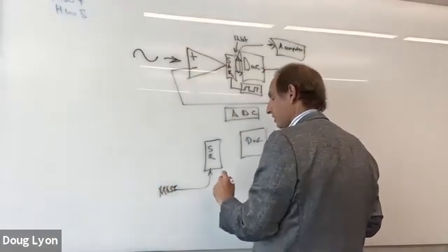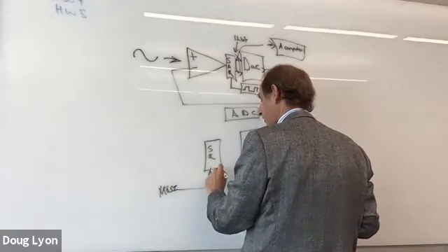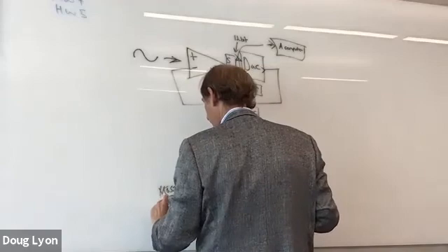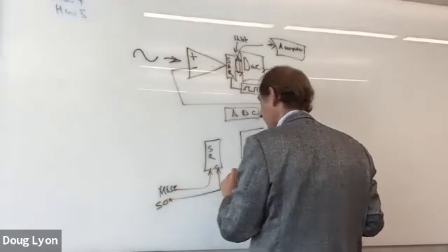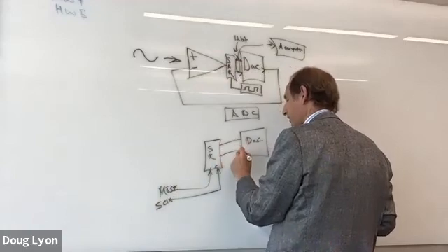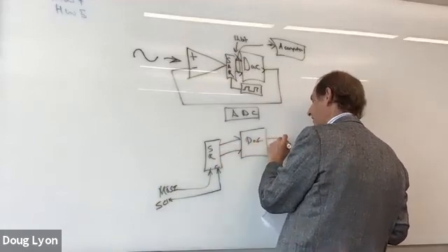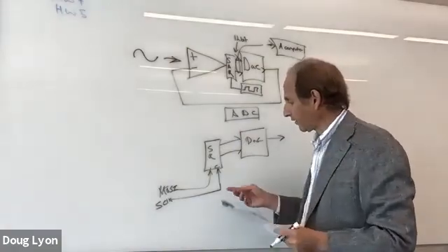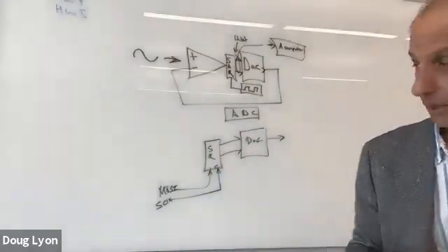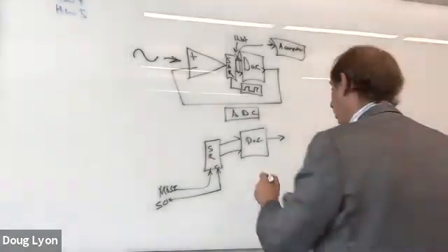The shift register needs to shift at a specific rate, so it needs a clock. So here comes the serial clock. And then when it's done, it can strobe its output directly to the DAC. And now the DAC can give us an output. So we have to have a serial clock if we're going to have a synchronous transmission of serial data into our little DAC.